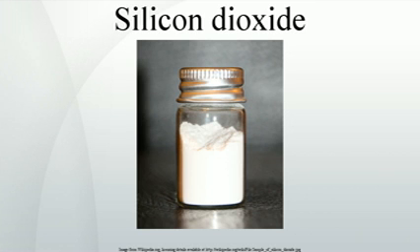On microchips, thin films of silica grow spontaneously on silicon wafers via thermal oxidation. This route gives a very shallow layer, approximately 1 nanometer or 10 Å, of so-called native oxide. Higher temperatures and alternative environments are used to grow well-controlled layers of silicon dioxide on silicon, for example at temperatures between 600 and 1200 °C, using so-called dry or wet oxidation with O2 or H2O, respectively.